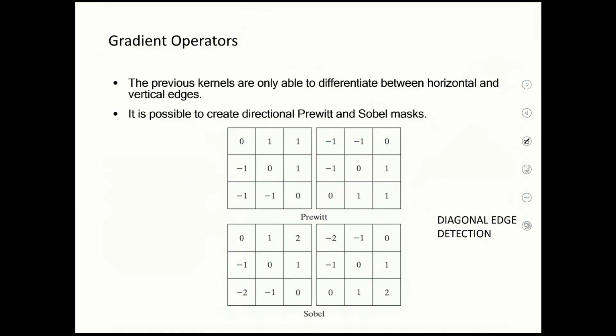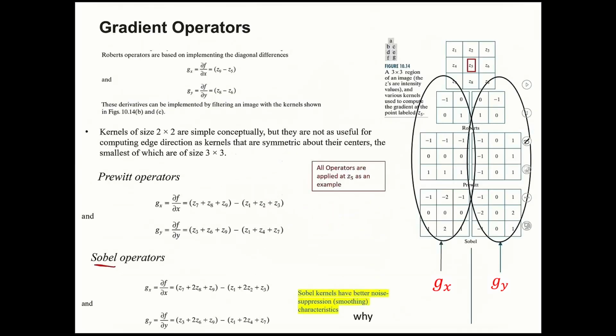Similarly, as we discussed before, the orientation of the filter is also important to detect edges at the specific angle that we want. So for Prewitt and Sobel, if I rotate it, this will detect the diagonal edges as compared to the horizontal and vertical. And how to find that this is diagonal? You have to find the similar elements along one axis, which will tell you how much the orientation is rotated as compared to the vertical one. The vertical one is our reference. So if you want to rotate by 45 or minus 45.